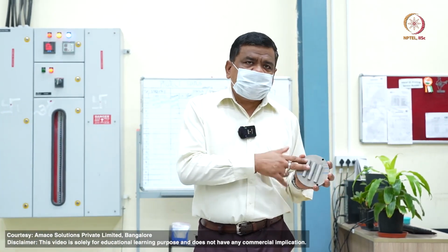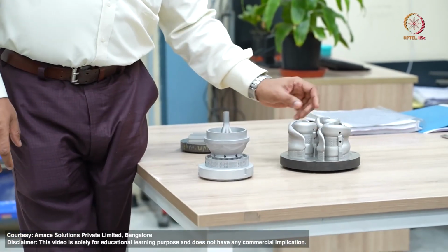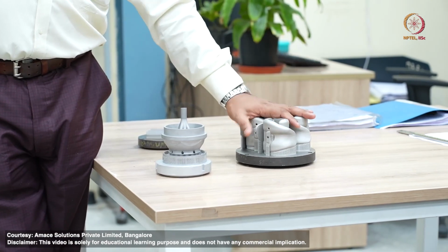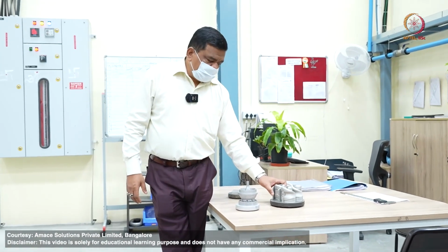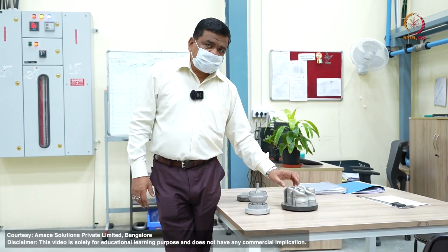What you see in my hand is a titanium-based alloy which has been printed, and these particular samples can be machined to get tensile samples and the typical tensile properties of the titanium samples. This is one of the cobalt chrome based materials which can be used for knee implant applications, and this is a commercial design of the knee implant. These particular knee implants have been manufactured here before they go for post-processing using grit blasting and heat treatment techniques here at MS.